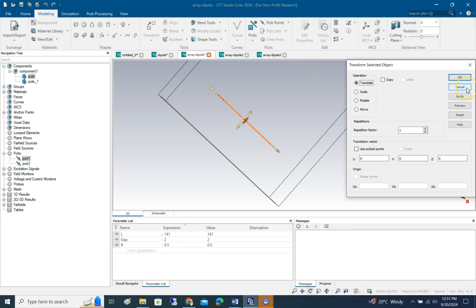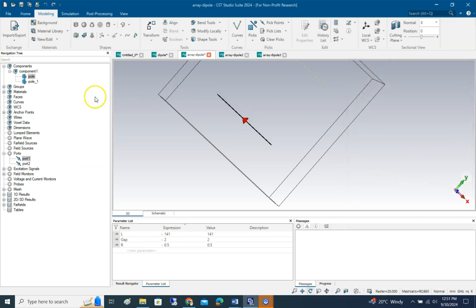So remember, I should have mentioned that before. When you copy the previously designed single element antenna, don't forget to copy the port. Otherwise, you have to define the port again, and that could go wrong. So don't forget to copy the port as well. Okay, so now that you have an exact copy along with the ports,